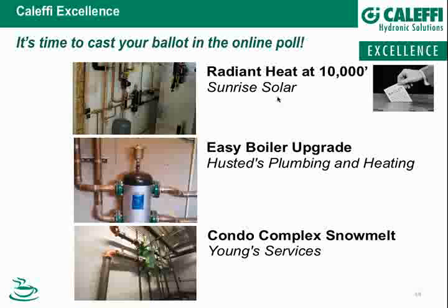Yeah. Well, again, it's a very fair question. I don't know of any industry standard on that. It's similar to saying, what's an acceptable safety factor when you size a boiler to a given heat load? Some people might tell you 10%, others might say 50%. I'd suggest to you probably plus or minus 10% would be reasonable. And again, it's not a scientific answer, but if you're looking for 10 gallons a minute and you're getting 11 or you're getting 9, the actual heat delivery performance of the circuit is really not going to be affected much by that.